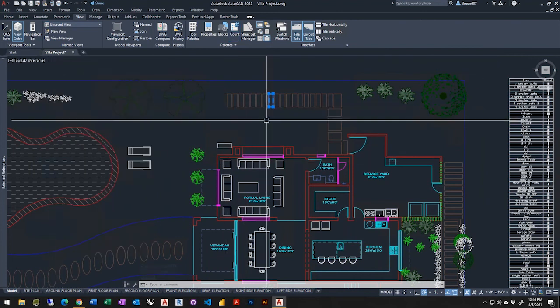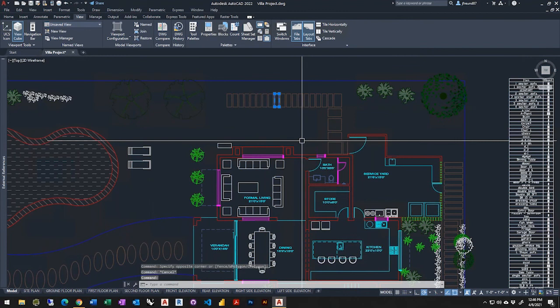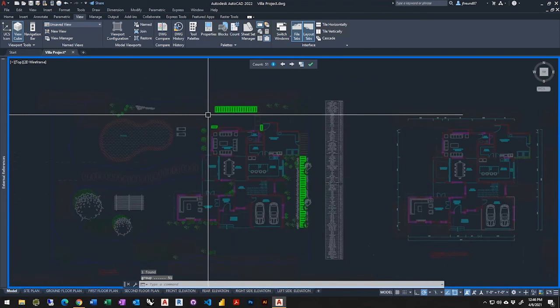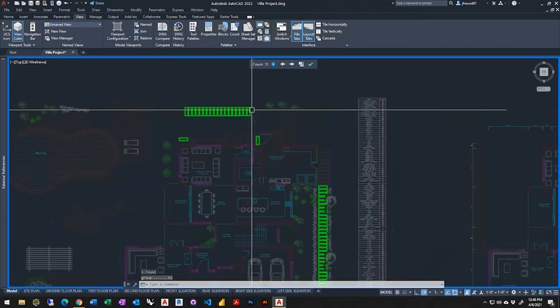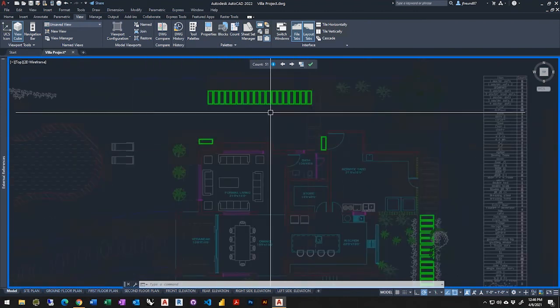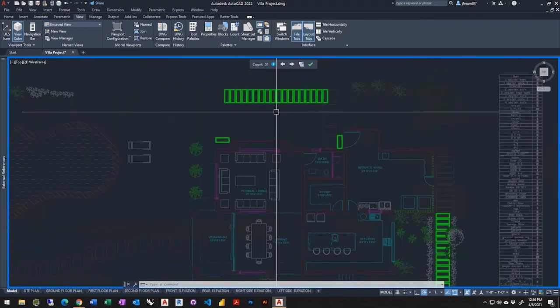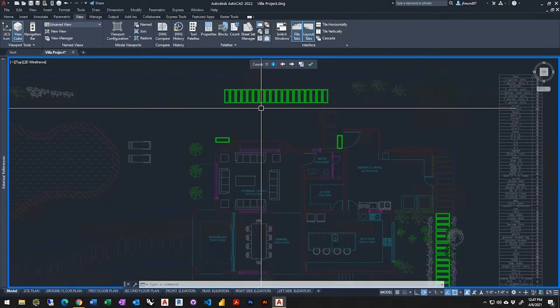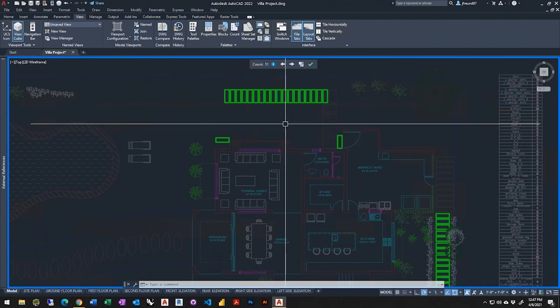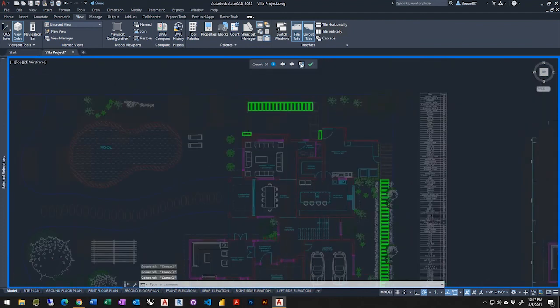So if I just have a piece of geometry selected, I can run the count command there, and then it'll look through the whole model and check and see, okay, where else does that sort of geometry appear? Or maybe one of these pieces was the original rectangle that was then copied to all of these different locations. And as you can see, you can insert the field count for all of those objects. You can cycle through all of the different objects that are in the drawing.